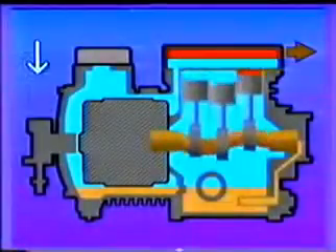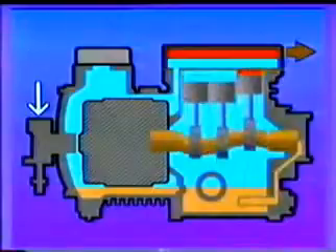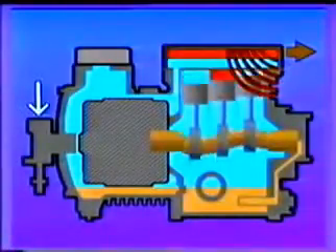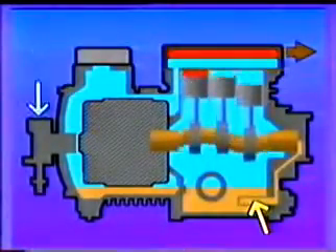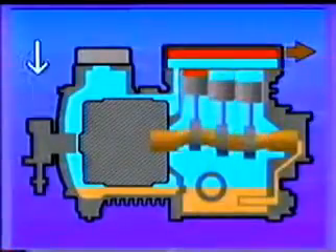Since the hottest point in the compressor is at the discharge port, heat from this area conducts through the cylinder walls. The high cylinder wall temperature will cause the oil to lose its ability to support a load, and the result is worn pistons, rings, and cylinder walls. This wear causes 2 major problems affecting compressor life. First, the fine iron particles left from this wear remain in the compressor oil and can clog the compressor oil pump screen, which further decreases the available oil for cooling and lubrication of the bearing surfaces.